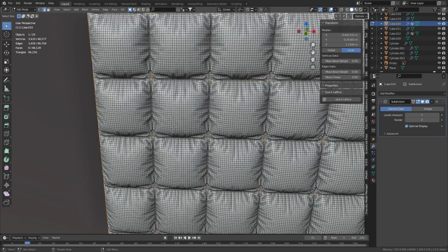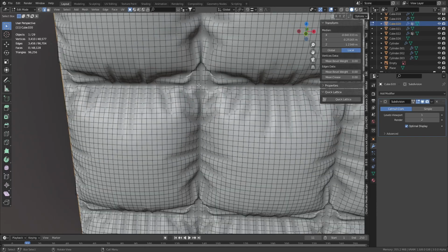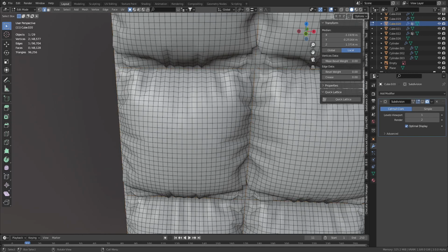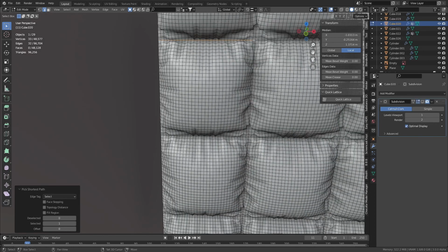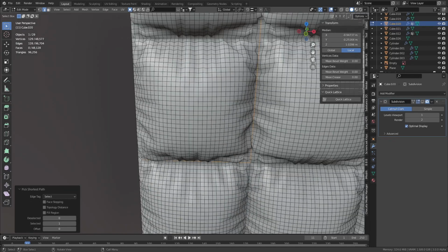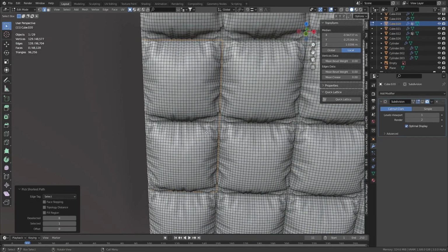So as you see in the reference that we have in PureRef, the door opened is this. So we need to select this part and separate it from other objects. So we need to select all these and separate this by clicking V, to rip these edges from the selection. So when I click V, you see that these edges are ripped from the selection.